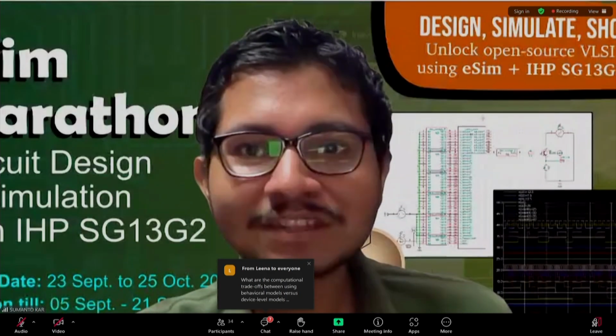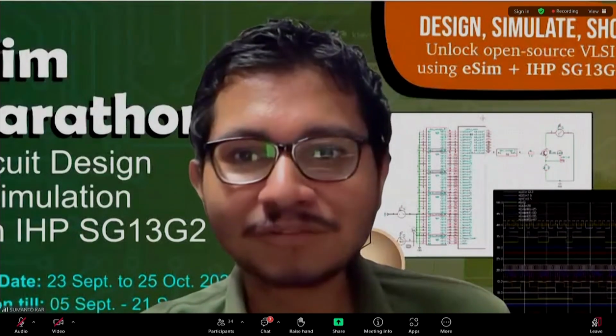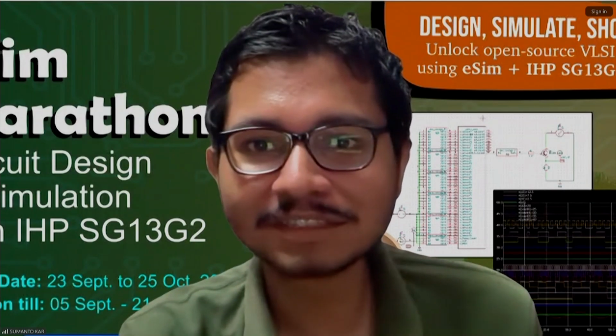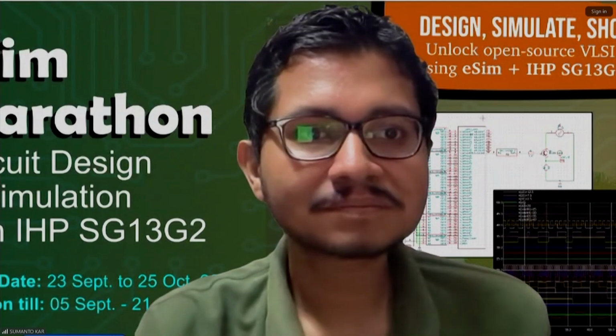Another question: explain how the modified nodal analysis method forms the basis of Ngspice circuit equations. This is the venerable modified nodal analysis. We use a very traditional approach. We create the admittance matrix with the modified nodal analysis type, and then use a sparse matrix solver.